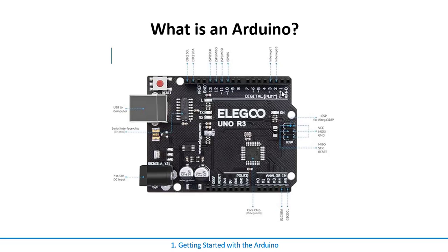But what we're going to do is use this to drive an LED. Luckily on here, pin 13 is tied to this little LED that's labeled L. Apparently they didn't want to write it out, but it's just L for LED. And here's the little resistor on it. So all we have to do is write low to this LED and it'll turn off, or high to this LED and it'll turn on. And let's just blink it at a common rate.